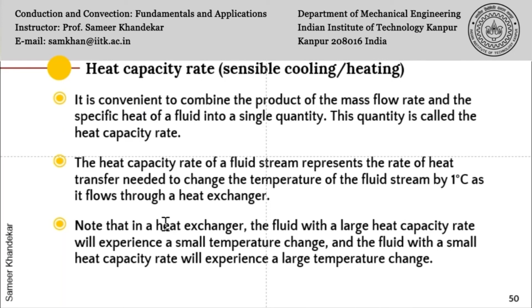So please note that as soon as you have a higher thermal mass, then it is natural to say that this particular fluid out of the two, out of the hot and the cold fluid, the one which has a higher heat capacity rate will have a smaller temperature change, and vice versa.